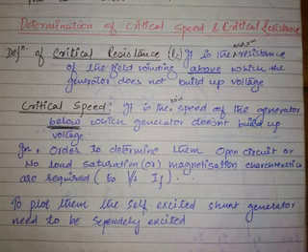Now, you know E is proportional to phi into N. E is proportional to phi N. It means the induced EMF depends on flux as well as speed. You want a strict relation between E0 and phi. If speed varies, will you get that relation? No. Speed should be maintained constant. If speed is maintained constant, only then can you know the relation between E0 and phi. That's why OCC should always be plotted at a particular, constant speed.